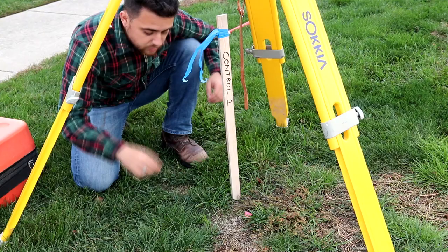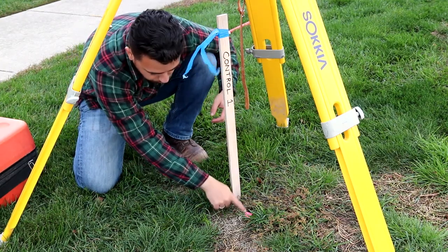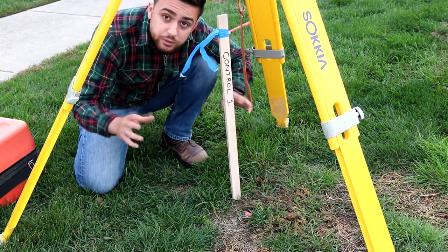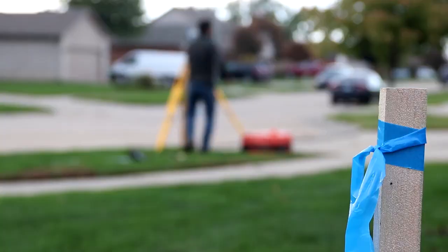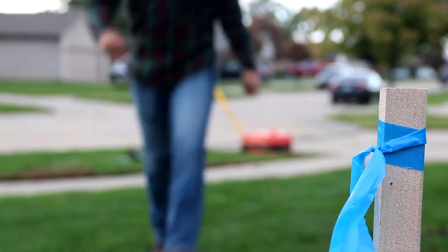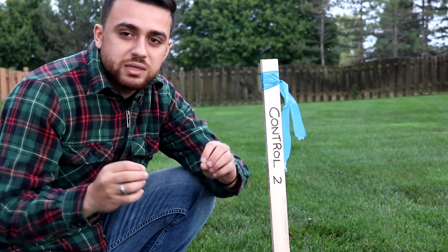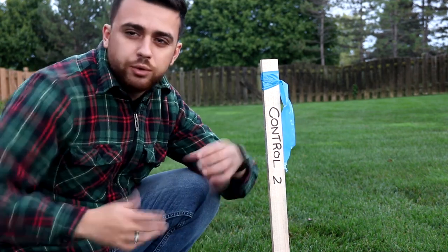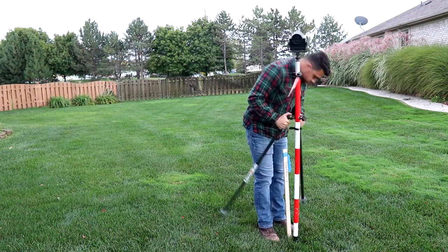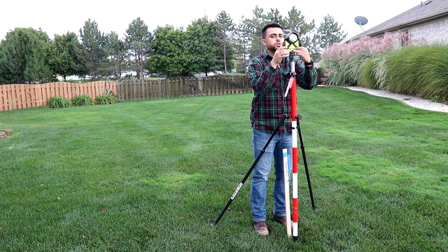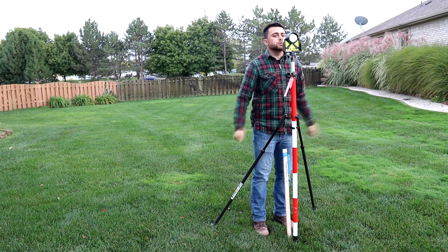Either method is fine. You don't have to have a data collector, it just makes things a lot easier. Now in terms of a control network, we only have one setup, so we're only going to need two points. The first control point is this point right here. I'm calling it control 1. The total station will be set up here the entire time. And over here is the second control point that we'll be setting up a backsite to. This will just be a fixed rod with a prism on it. Okay, should be good just like that. I'm just going to point this in the direction of the total station.